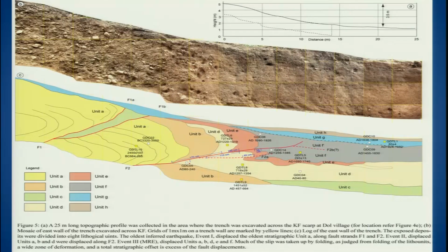After detailed cleaning and demarcating the boundaries between the different units, we mark the fault, which goes right up to this point here. A few doubtful areas, which could be depositional or erosional contacts, were marked as such. One thing is very sure: at places we saw very typical notches developed within the sediments, which could be a result of a bulldozing effect and displacement along the fault strands.